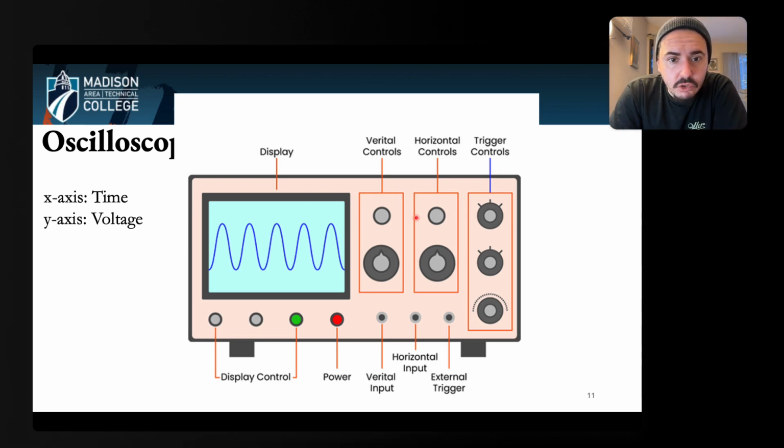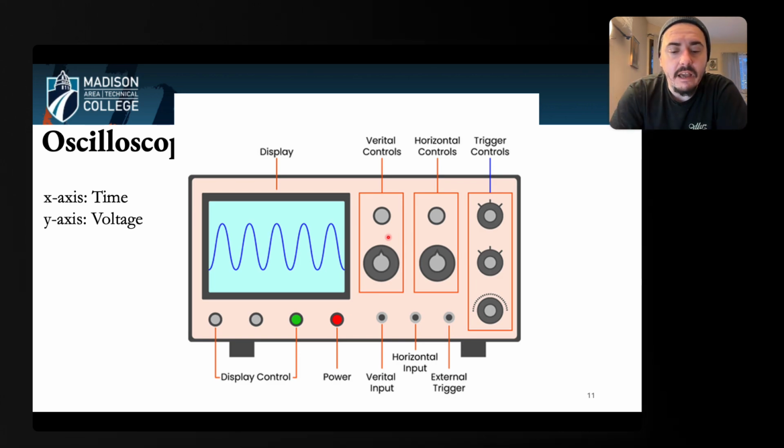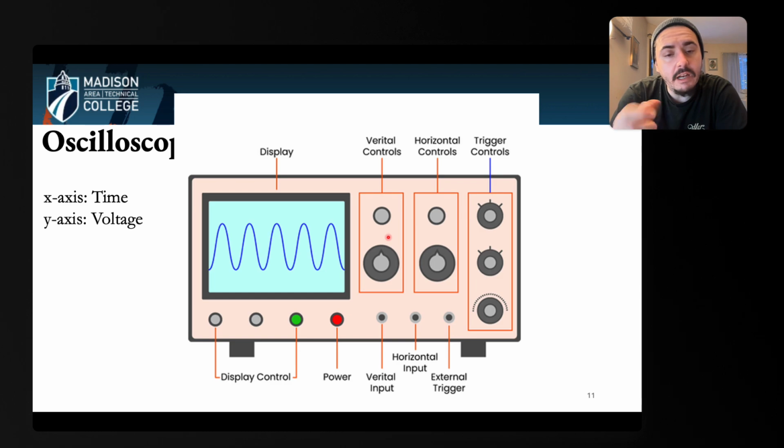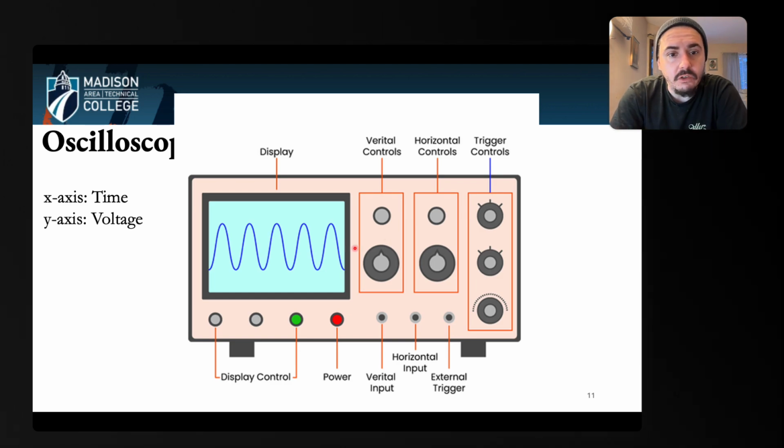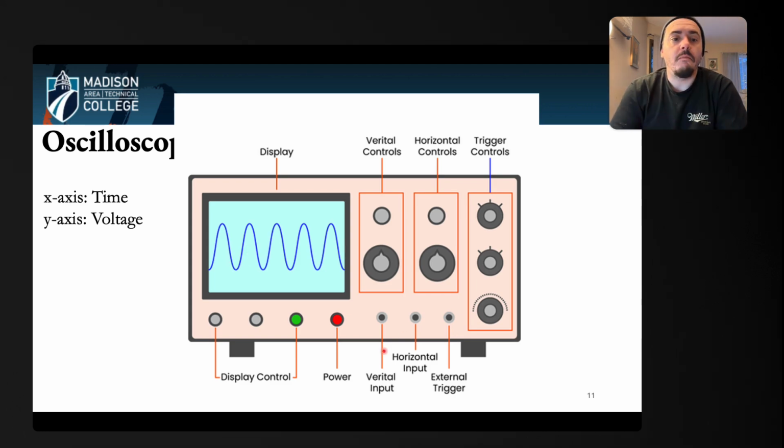Then I also have these two controls here, so dials. I have basically windows for the x and y axis, and I have typically a coarse tune and a fine tune in order to get the window to where I want it to be. And then I have some trigger options. So basically I can trigger when I start to take this measurement in order to record the wave function here. There are also multiple inputs.